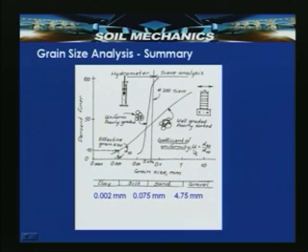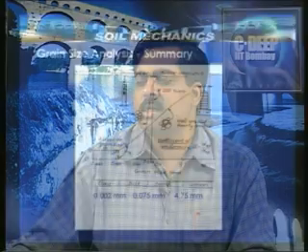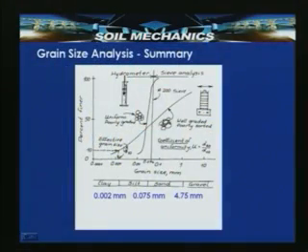The coefficient of uniformity is Cu equal to d60 by d10, and the coefficient of curvature is d30 squared divided by d60 into d10. We also said the effective particle size is indicated as d10, which indicates that 10% of the particles are finer and 90% are coarser than this size, and d50 is the average particle size.